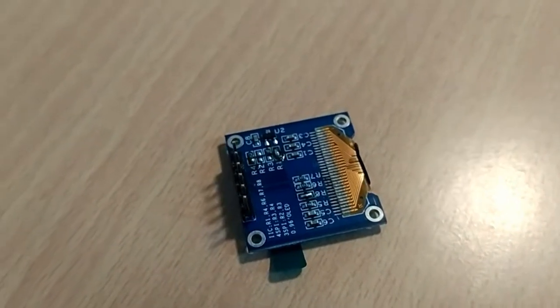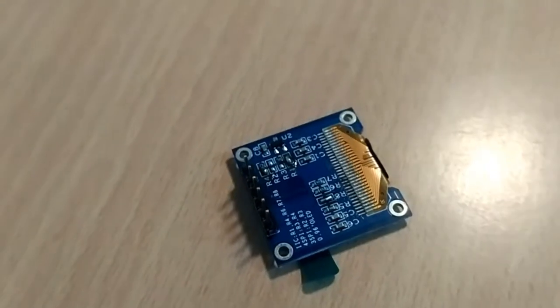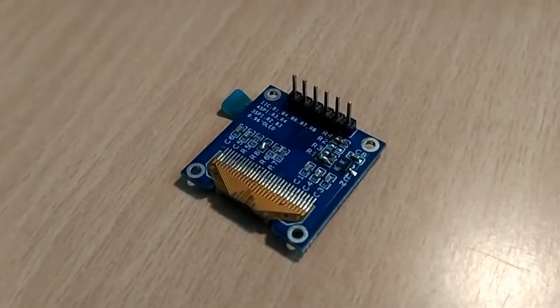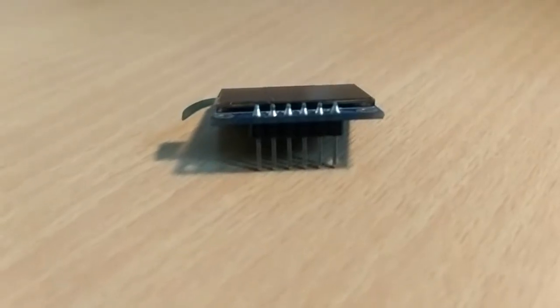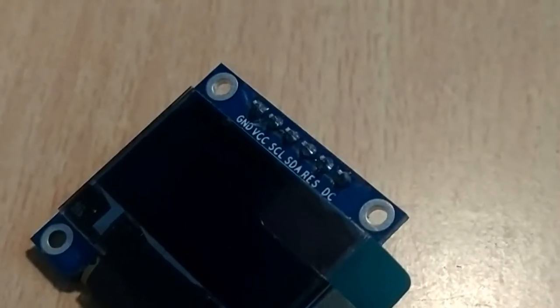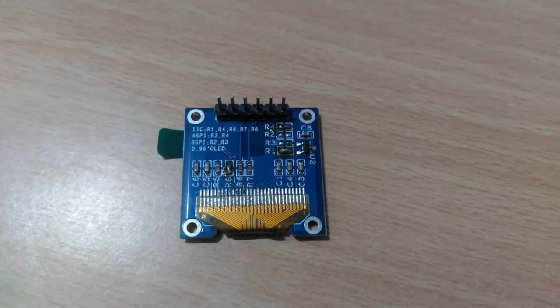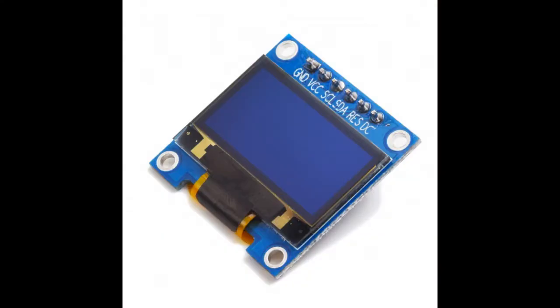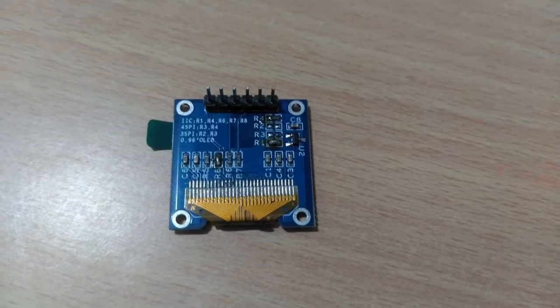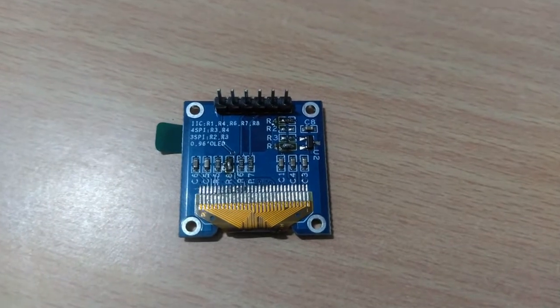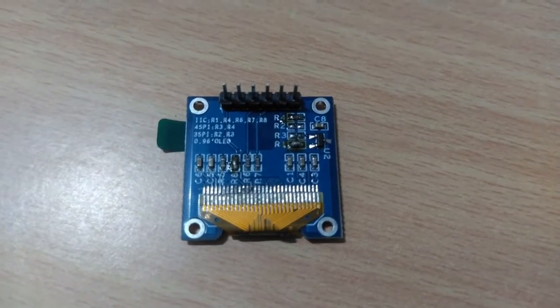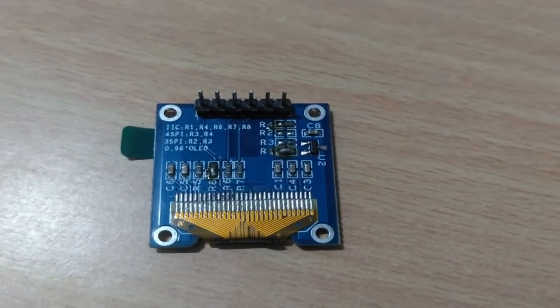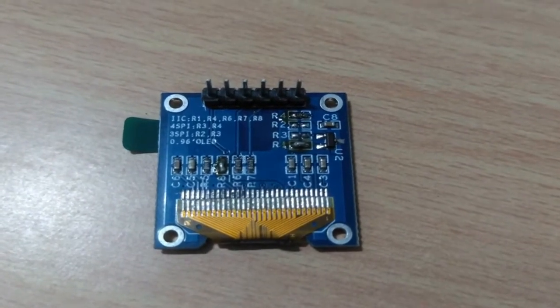First, we are going to take a closer look at the OLED display. My OLED display is a 128x64 monochrome SSD1306 driven I2C 6-pin Arduino compatible display. Don't worry if you have an SPI interface display. You can make it I2C by shifting the resistors on the backside of the display. It also has a reference where the resistors need to be placed.